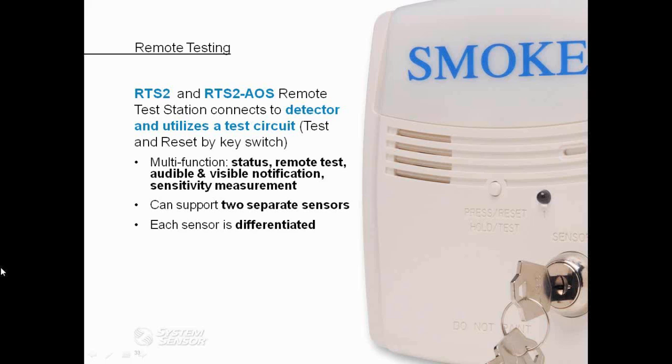And if you're using our 2-to-1 capability with the 2 sensors back to the 1 power board, you have the option of using this one accessory to monitor both of those separate sensors. So the key allows you to select sensor 1 or sensor 2 in order to perform the push button test, and then you have 2 separate LEDs that will differentiate the status between each of those installed sensors.